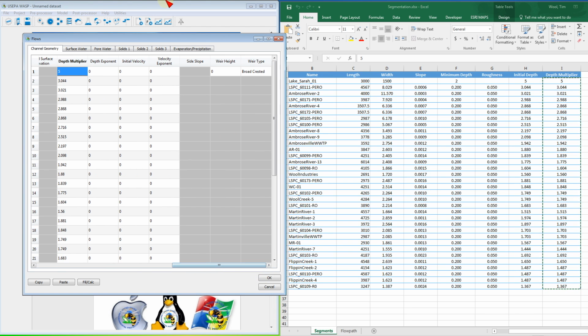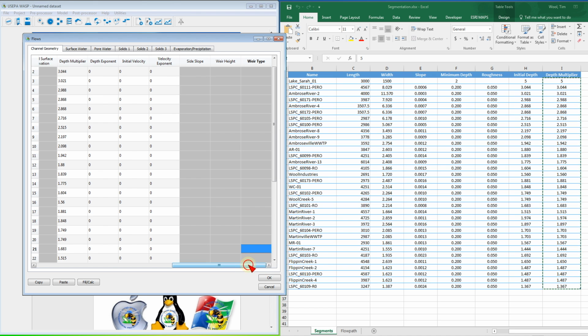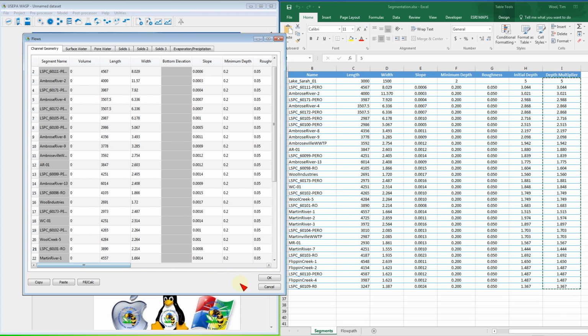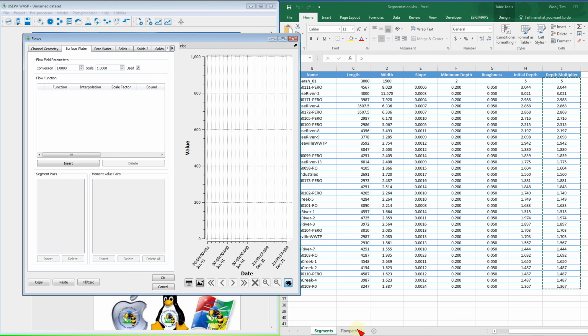Once we're done with that, we've set everything up. We're setting our weir height to 5 meters at the bottom, so when the depth of the lake at the bottom goes greater than 5 meters, water will go over that weir. We also could have not put a weir in there, and instead put an internal flow boundary and had flow coming out.